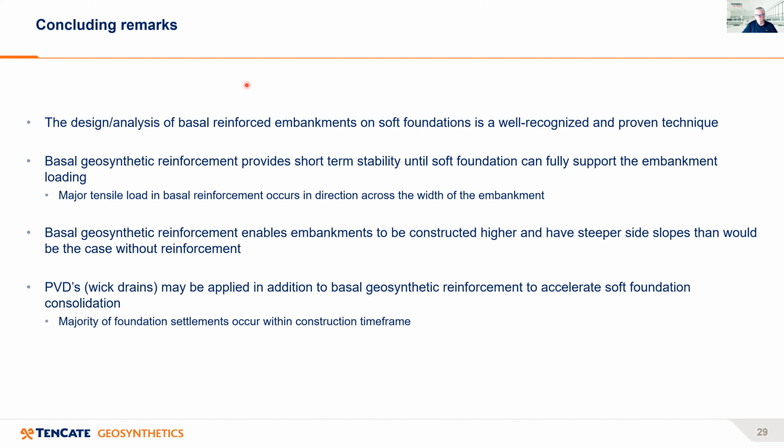Basal geosynthetic reinforcement enables embankments to be constructed higher and have steeper side slopes than would be the case without using reinforcement. Now, wick drains may be applied in addition to basal reinforcement to accelerate the soft foundation consolidation.